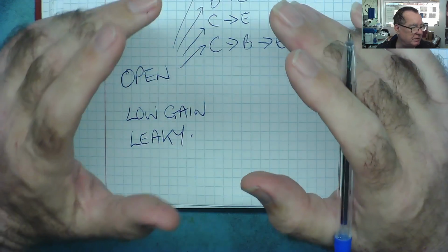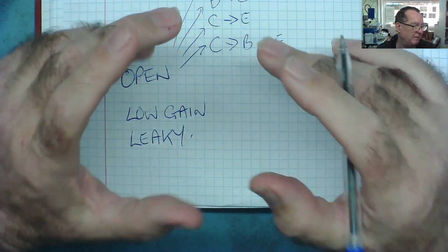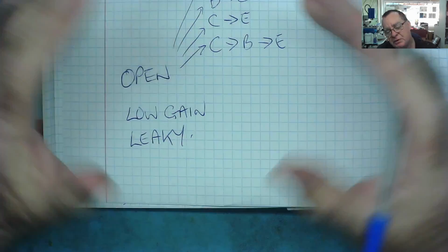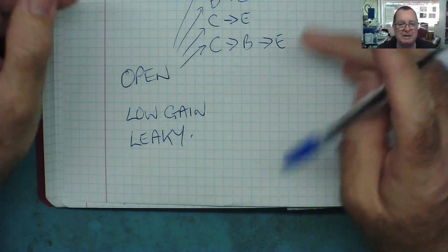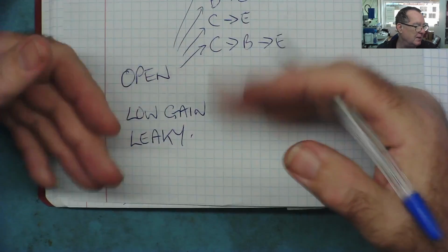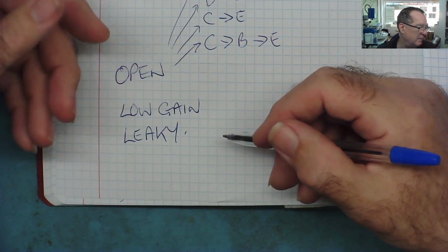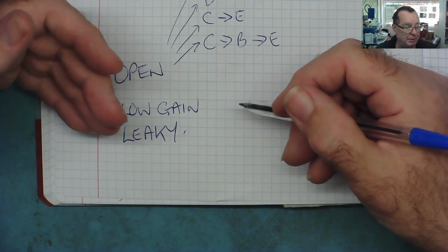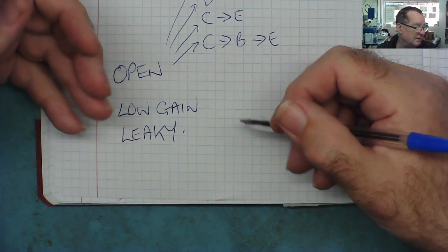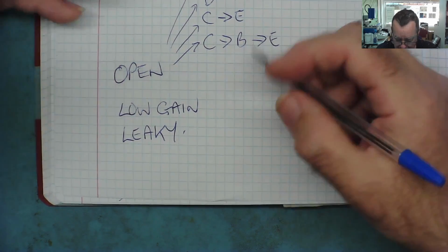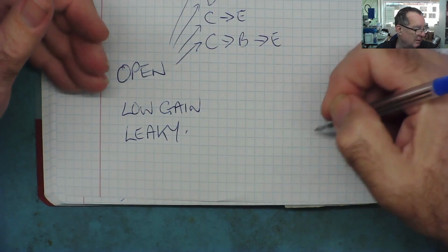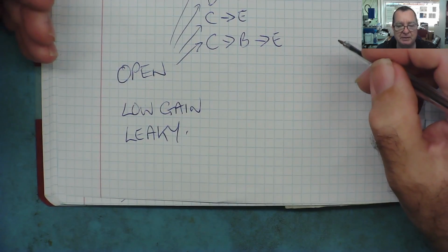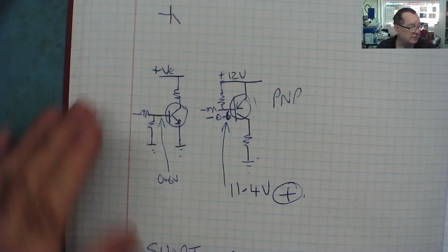So although this is all you need to know about transistors to fix stuff, I will need to do another video specifically for those types of circuits that discusses the problems with noisy transistors and problems with gain. In amplifiers in particular, you have a number of transistors all in parallel effectively handling a load, and the gain between the transistors doesn't match. Two other things I'll mention.